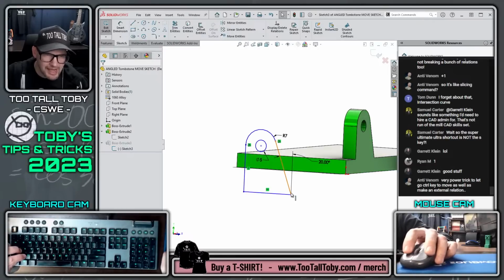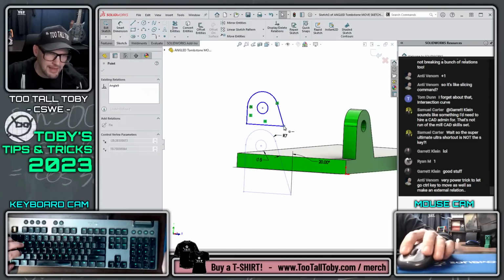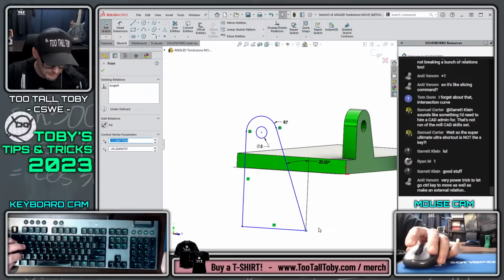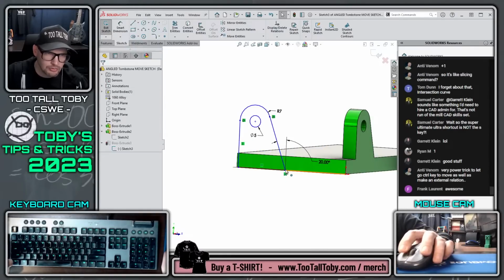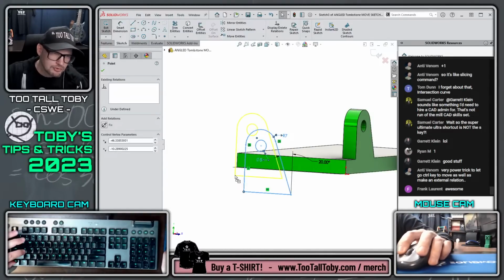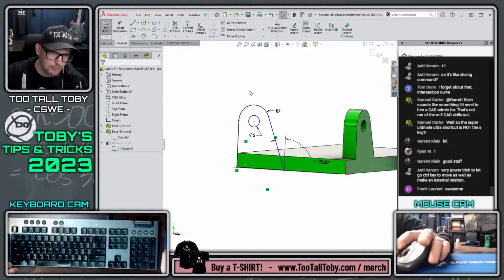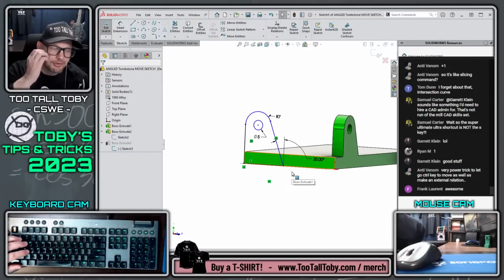Now, if I just try to drag this geometry, things are going to go haywire. I'm sure we've all been in that spot before. Like, no, I just want to put this on here, but I want it to stay the same shape. Well, what you could do is window, hold control, drag, let go of control, drop, and it retains the same shape. Or you could even window, hold control, drag this point onto this corner point here, let go of control, drop, and now it picks up that corner relationship, and you just need to add that one final dimension. So this is absolutely mind-blowing.